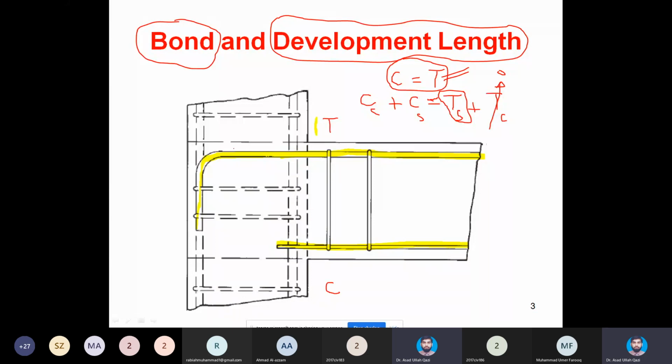because the steel anchored within the column is required to yield at the face of the support at this point, and we know that as per tension controlled under-reinforced cross section we must have tension steel strain greater than or at least equal to 0.005. So this is our tension controlled under-reinforced requirement. And on the compression face, we have the requirement that once concrete crushes at the extreme compression fiber approaching the limit strain, steel at that instant will be either at 0.005 or bigger.